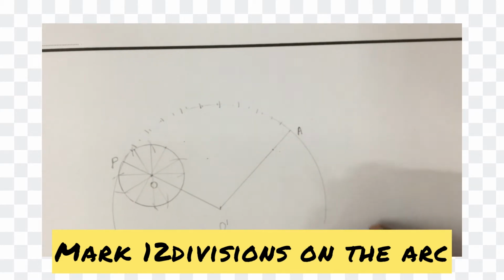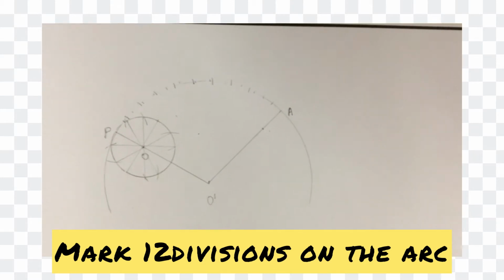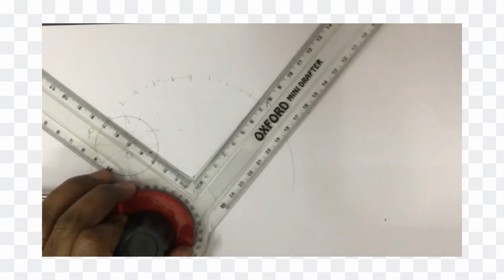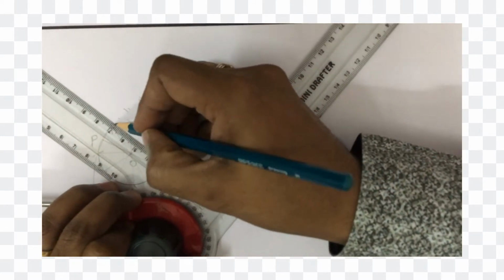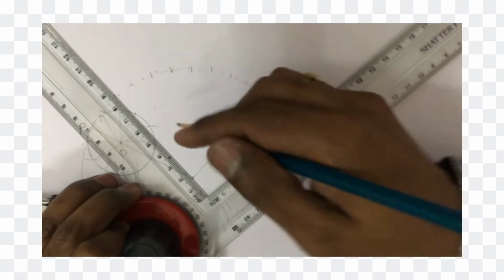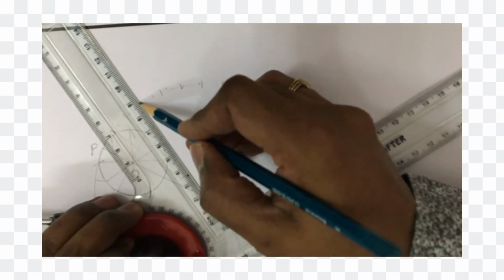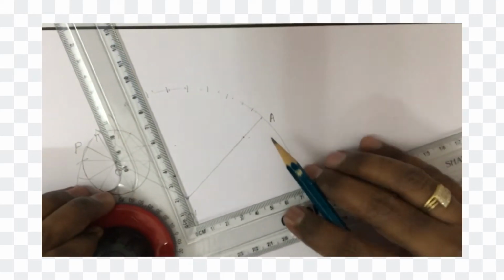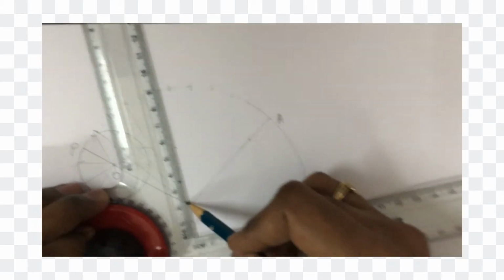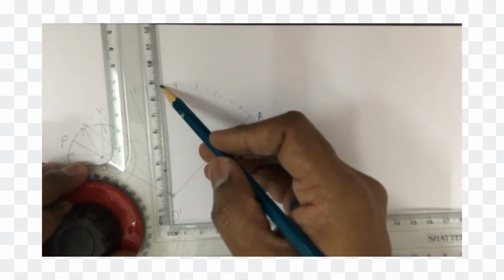So you are supposed to divide this into 12 equal divisions, keeping in view, and draw all the points from this using H pencil. So let this be 1 and 2, 3, 4, 5. So dear students, if you are not getting, use trial and error method to draw these arcs.